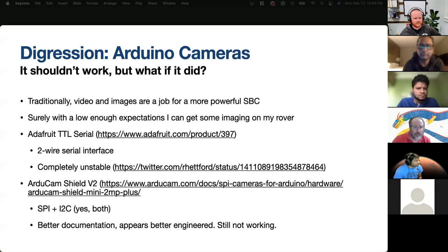The SPI is several orders of magnitude faster than I2C. So you can run it at several megahertz, 10 megahertz, 20 megahertz, but I2C, I think I have not seen it go more than 1 megahertz. Yeah, that could be a part of it, but wouldn't you sort of guess that everything would operate over the faster one?